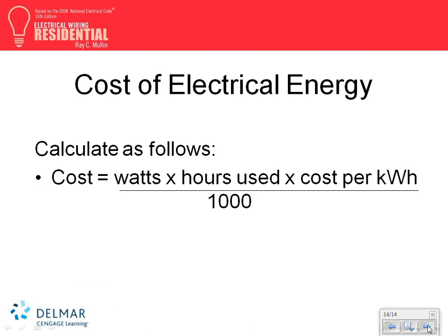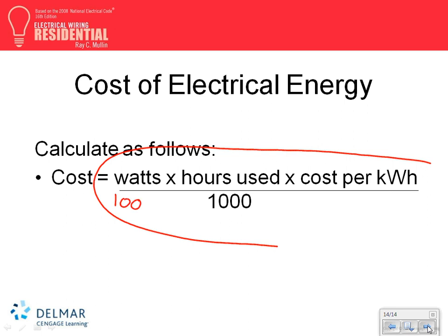So that's the cost of power, guys. This is a formula we did in the calculation. You take the watts multiplied by how many hours, by the cost per kilowatt hour, and you calculate your value. So if I have a 100 watt lamp and I run it for 60 hours and multiply by the rate, cost per kilowatt hour is $0.07, which is 7 cents, that will get you how much this 100 watt lamp costs if you run it for 60 hours, let's just say 6 hours instead of 66 hours.